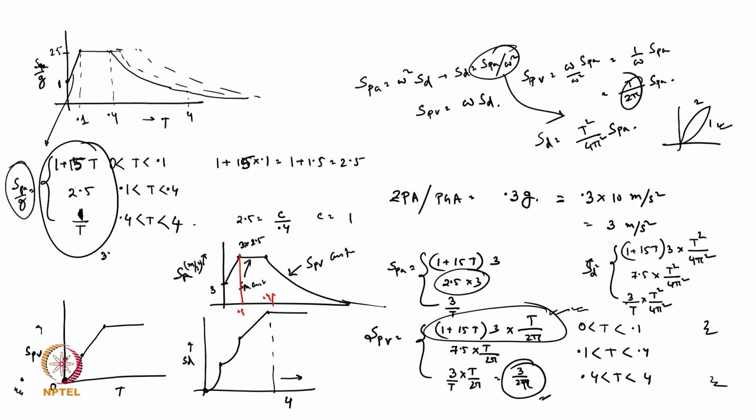Exactly, the displacement. You see, the HD value becomes so high. Maybe you are sitting at the top, your building does not feel that much force, your columns are not feeling that much force, but you are like in a merry-go-round, going like this, swinging. So that will create a problem. For example, you see that problem in the case of a wind turbine tower also, where at the top there is a very heavy mass.